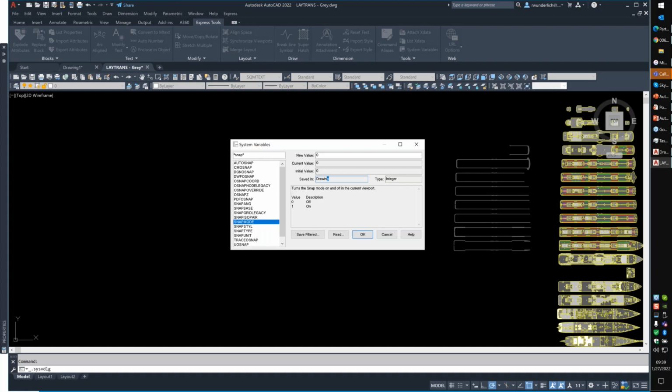Updating all items on palettes to point to a different path after moving them. Again, Harold, I will cover that in the tool palettes one. There's two ways to do it. Either you have to go in and individually do it, or you can actually open up the tool palette as a notepad document and do a find and replace on the paths. I find that's usually the easiest one. Your snap units, again, this is saved in the drawing. So that's a drawing specific variable, so it only applies to the drawing you're in. Hopefully that gives you some information, Gustavo.